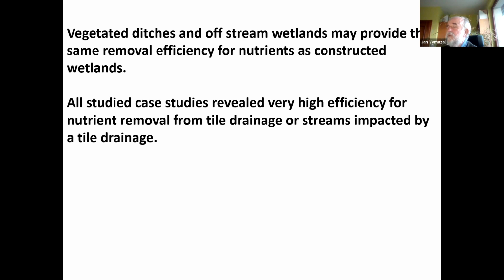And in general, I can say that all studies, both from the literature and also our studies, show the very high efficiency for nutrient removal from tile drainage or small streams which are impacted by the tile drainage, because you cannot treat the big streams. But if you have small streams, especially in the upper reaches, then it's possible to treat the whole stream, and with relatively very cheap operation and maintenance costs.